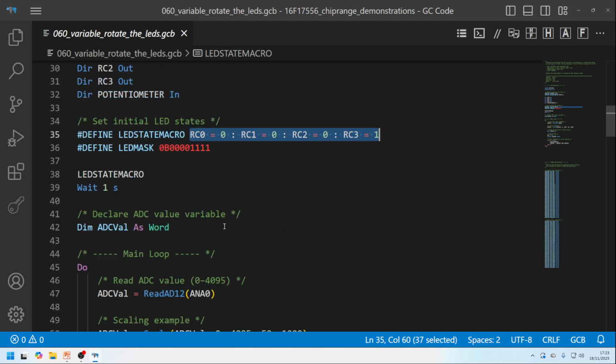Now, I also defined another constant called a mask. I said I was going to do bit masking, so this is a bit mask that says, essentially, for every bit of the bits 0, 1, 2, and 3, they're set to 1. I'm going to use that mask in a moment to strip off all the other bits. I'll explain that when we get there.